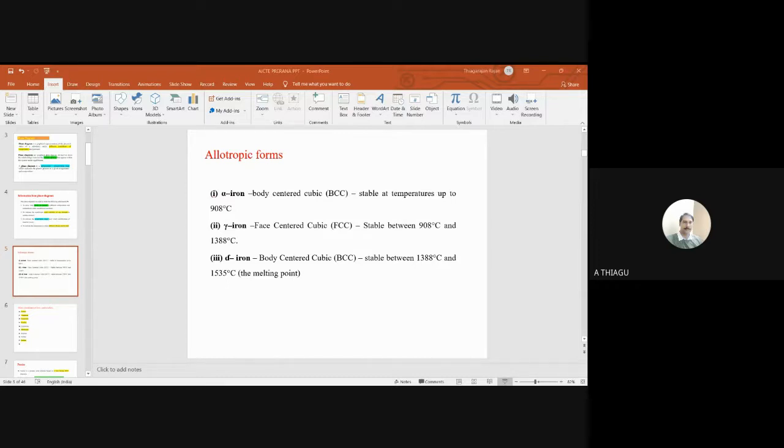So this is a good example for hypo-eutectoid steel. You can find the proeutectoid is the appearance of white color. Okay. So once you observe in the microscope, you can find this structure only. So the green colors are highlighted as proeutectoid and the remaining red color is formed by the carbon in the form of Fe3C, cementite. So alpha and cementite is called pearlite. So we can say it is a pearlite structure.